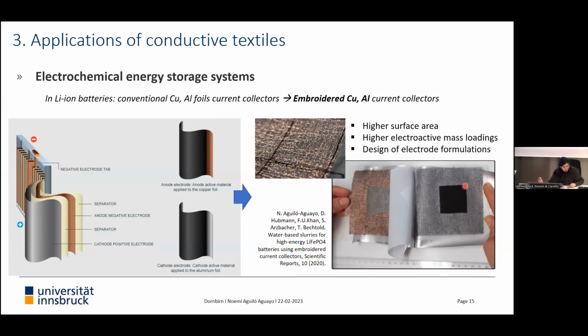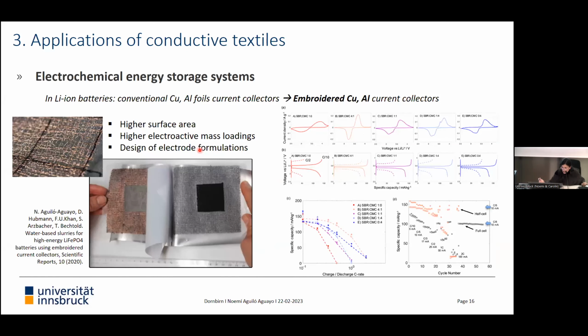For sure, we have to design thick batteries. Usually all these layers, you have to imagine that they are very thin because of the limited addition of the electroactive material. And in our case, our idea was to use thicker electrodes to increase the energy of the batteries. But we had to design new electrode formulations, and this is what we investigated also now.